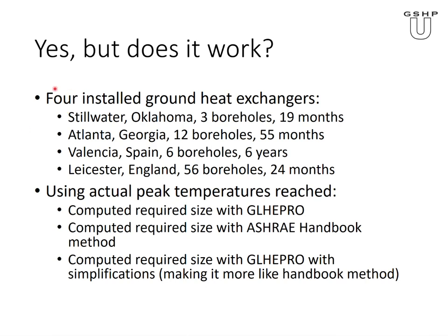So, only specifying for Stillwater the 3 boreholes and the distance apart, right? And then we used GLHEPRO and said, oh, we have a 19-month design period, what size would we have to achieve? We also used the, quote, hand method in the ASHRAE handbook. And then we sort of handicapped GLHEPRO with simplifications to make it more like the handbook method. You can't perfectly match it, but you can sort of partway match what's going on in the handbook method. That's what we tried to do.